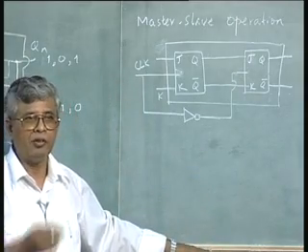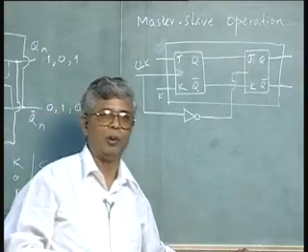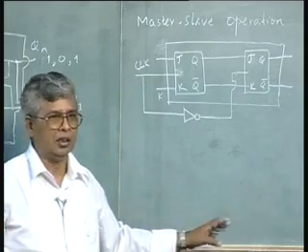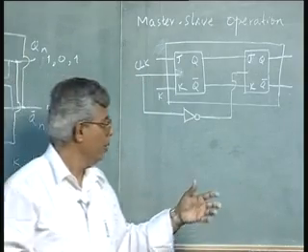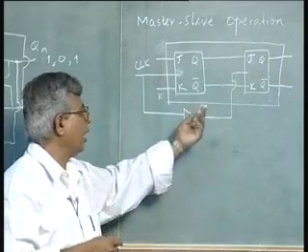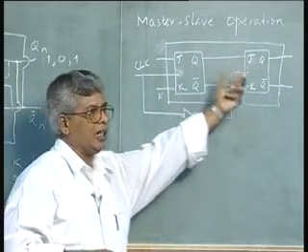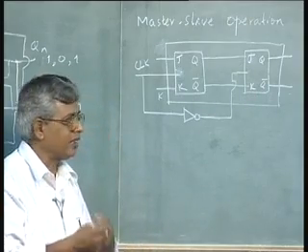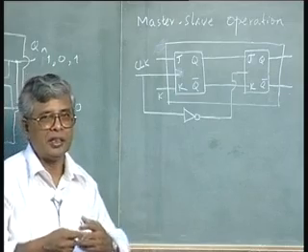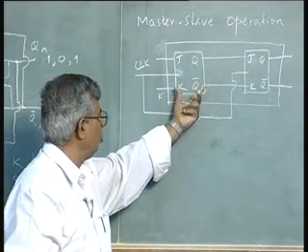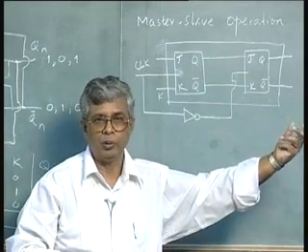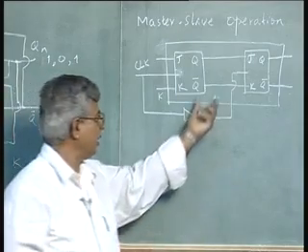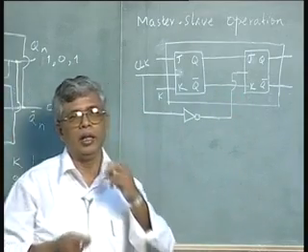Very unlikely, except that then we are talking of today's technology, Pentium 3, Pentium 4 processors, where we talk about gigahertz operation. Whatever it is, I do not want to question your need. Supposing you want to operate at a clock rate which is faster than the propagation delays which two flip flops can allow, why should I be restricted in the speed of operation by having to pass through two flip flop hardware? Why should I unnecessarily increase the propagation delay of the path if it is not required, plus the fact that there is extra hardware required? That makes you think whether it is the best solution.